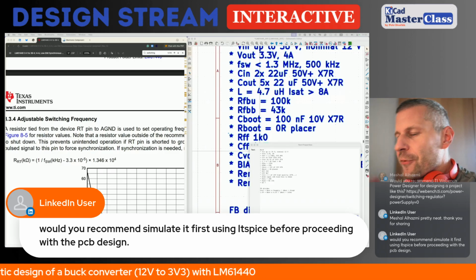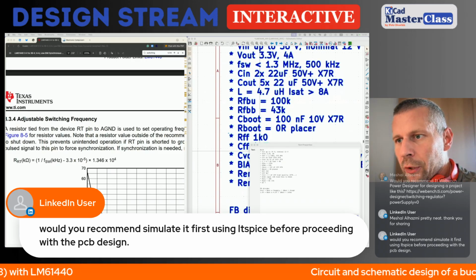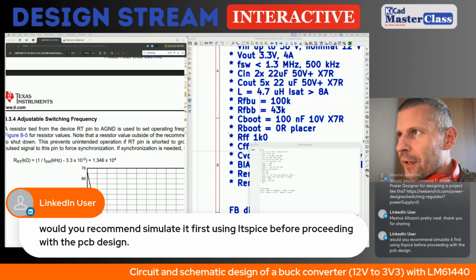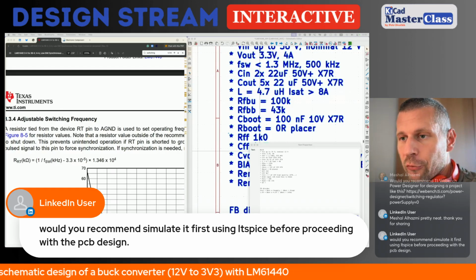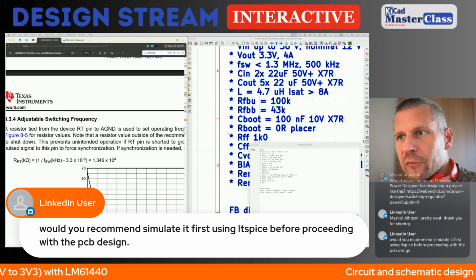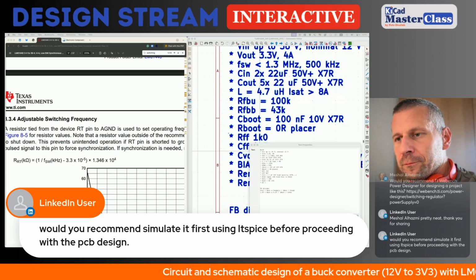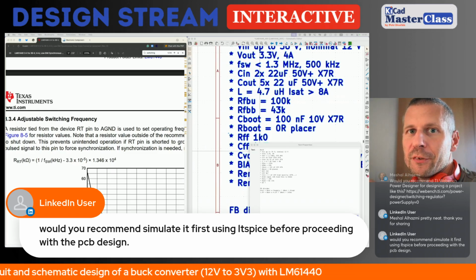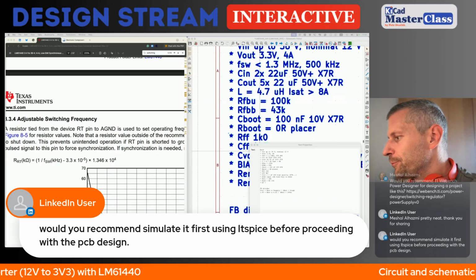So if you want to simulate the circuit with LTspice, you have to choose components which have models compatible with LTspice. So either you have to choose, let's say, Analog Devices or former Linear Technology. Usually all their models will be compatible with LTspice, or you can choose from the majority of reliable manufacturers, but you don't have the SPICE models. So yeah, you have to balance this.